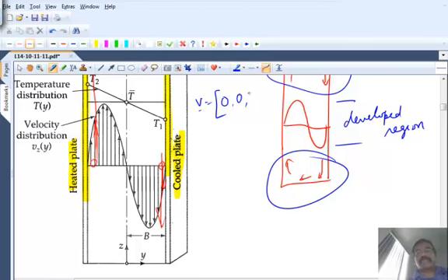Vz as a function of y only. So once again, we get a one-dimensional flow. That's an assumption, that's an approximation. That will be true in the middle zone. Now, if you set this up in Comsol, you need to select a finite length. But if you select the slit to be very thin, you can achieve this one-dimensional flow and compare it with the analytical result that we are going to get.